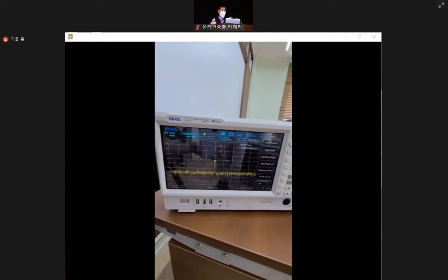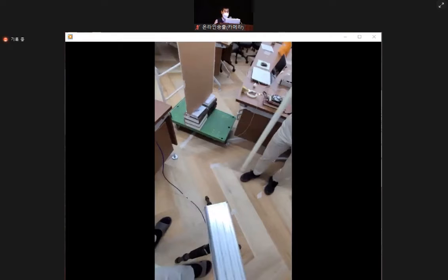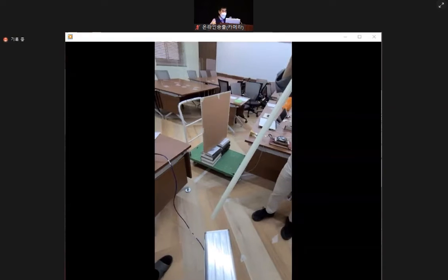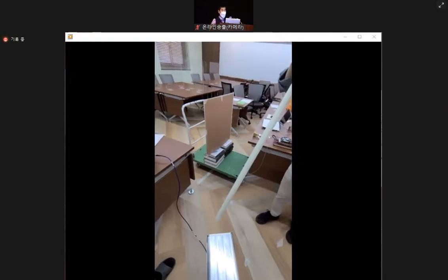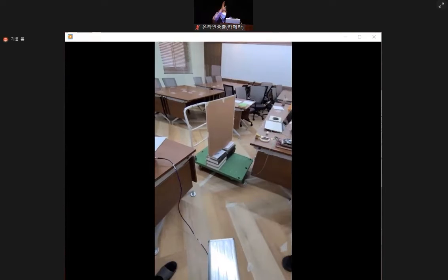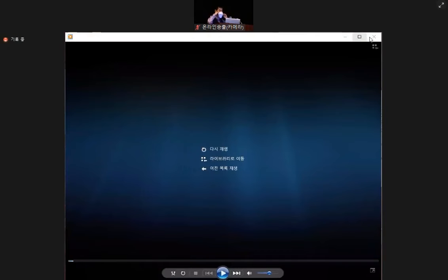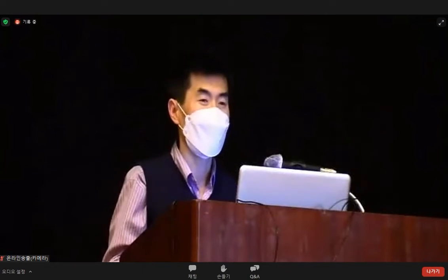By moving the probe to the upper angle, it's hard to read the tiny numbers of the signal strength on the computer there. But the power has definitely gone down, telling you what we expected. At the 45 degrees of observation, that was the best and highest in strength, around minus 40 something dBm. But at other angles, such as 20 degrees or 60 degrees, it will go down by 10 dB like that, or more than 10 dB.